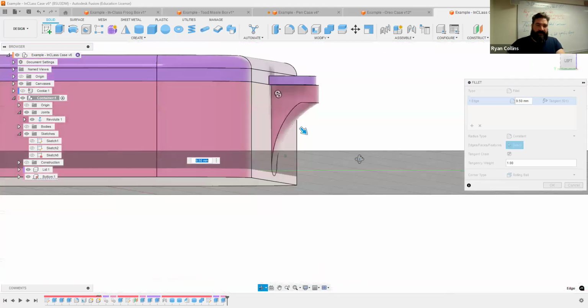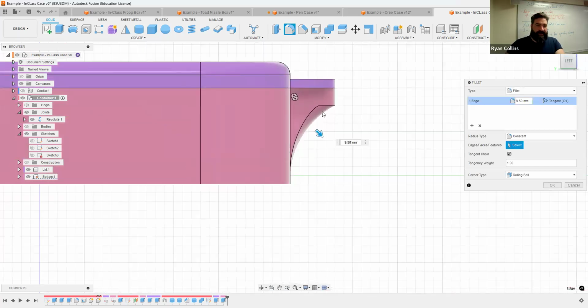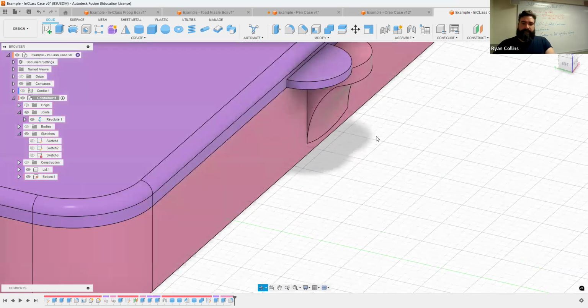So with doing something like that, now it's at such an angle to where I wouldn't need supports underneath this print. So just like we were discussing before, ways you can save material, ways you can both speed up your print and also save material. If I don't have to print a scaffolding, a support for that, then I don't have a bunch of wasted material. Cool. Let's do the same thing for the top.